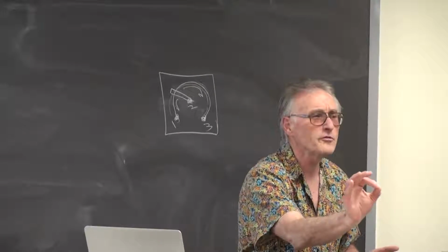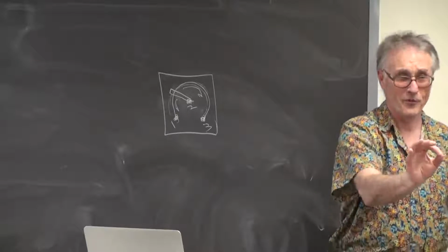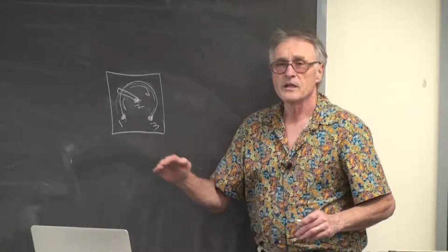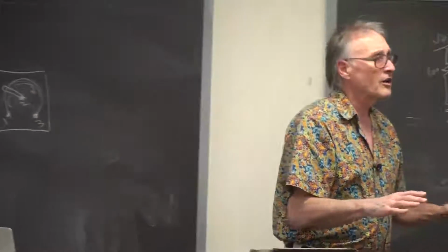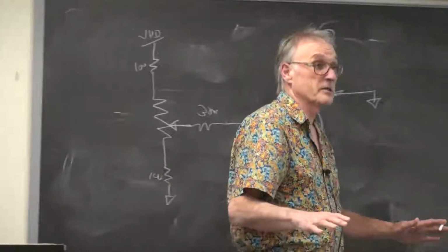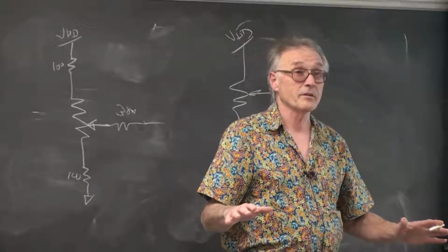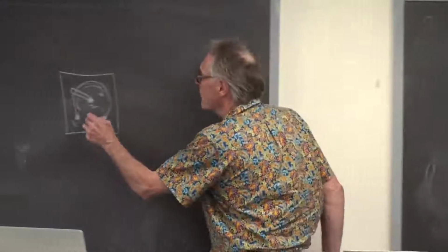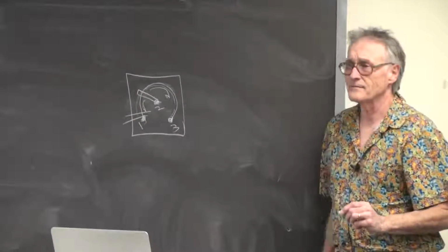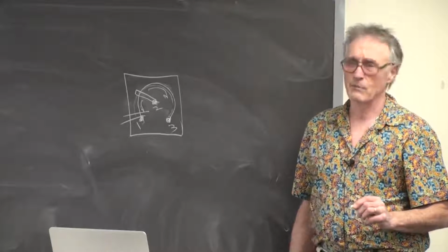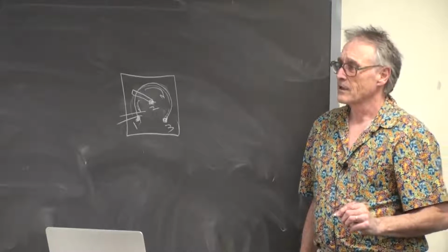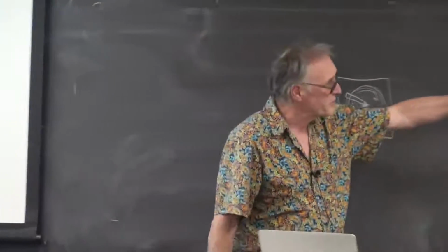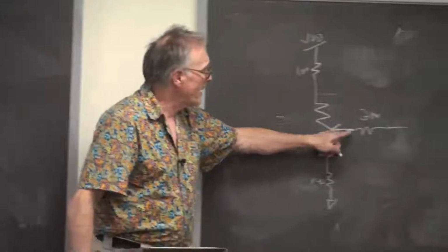Just before you do that, 1 ohm before you do that, just as you're bringing this down to the last point, you suddenly have a very low resistance. All the capacitors in the power supply are still charged, and it blows out the potentiometer. It actually takes this polymer strip and blows a hole in it. And then it doesn't work anymore at all, ever. So think carefully about how you're hooking this up, or put protection resistors top, bottom, and here.